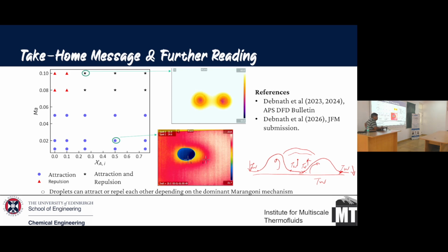It's a kind of ballpark. What we can see is the two droplets are actually approaching. So what is happening? Probably some kind of viscous dissipation is happening at the surface. Yes, that is one force, and there is one force which is trying to attract or repel. What is the order of magnitude? Typically, because the size of the droplet is really small, we can expect the viscous dissipation to be quite negligible. Given the main driving force here is solutal Marangoni, that is stronger. I think it's about 5 or 6 orders of magnitude stronger than the other things.